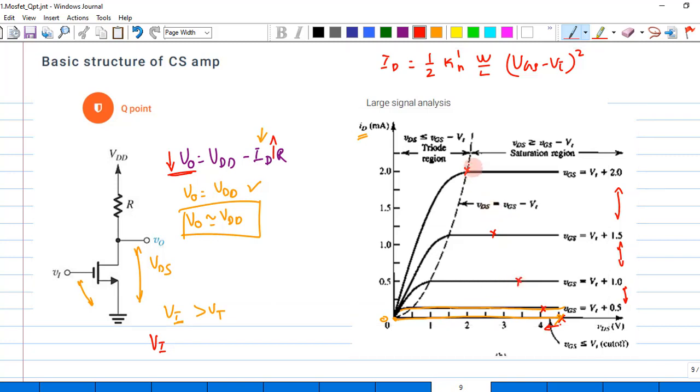So now, for a particular value of VGS, you can see that right from cutoff, I just jumped into saturation, and I have moved all the way through the saturation region to a particular point. This is a special point where I am at the edge of saturation. For the corresponding input, I am currently at the edge of saturation, and the corresponding output voltage can be read by taking down this value, which is around 2 volt. So that is my corresponding VDS value.